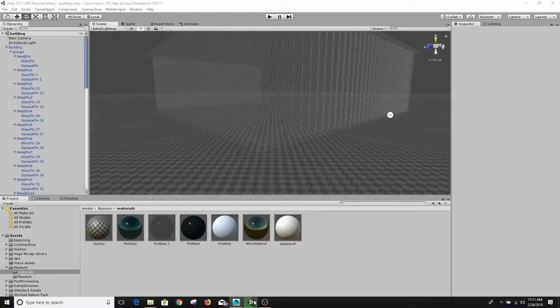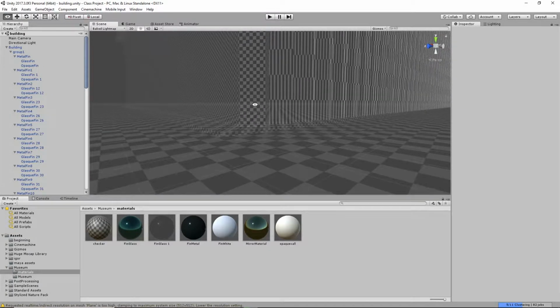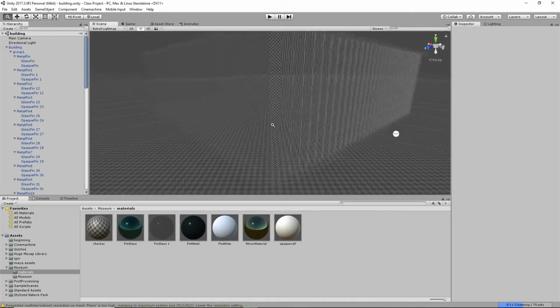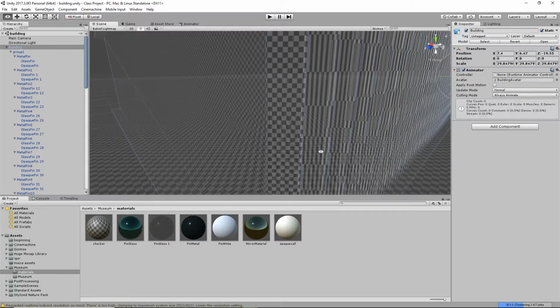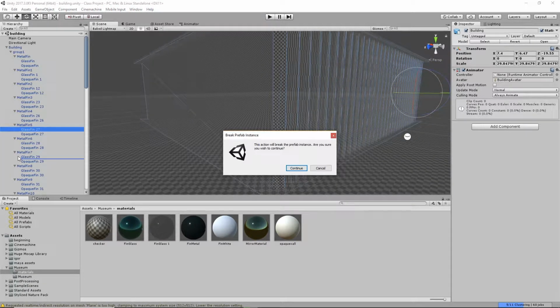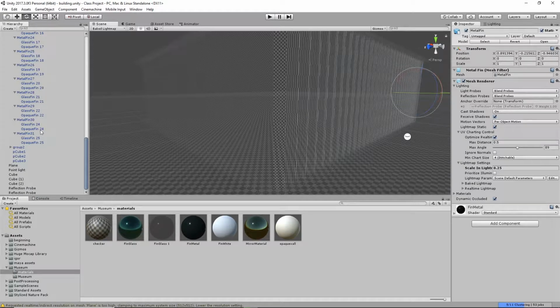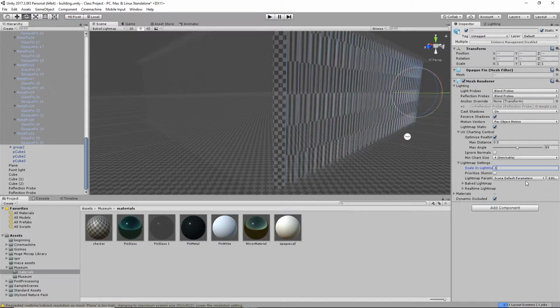And now if we open up Unity, we'll see it reflect. And you'll see by doing that automatic texture mapping, my UVs for this particular fin and for the roof and everything else got laid out square. So now I have more control. So if I select the building, let's see, which fin am I looking for here? Whoops, cancel. Let's just select them all. Set the fin's scale in lightmap to 0.1. Yeah, that looks pretty good.